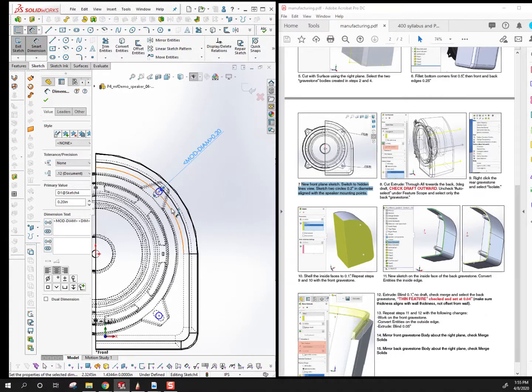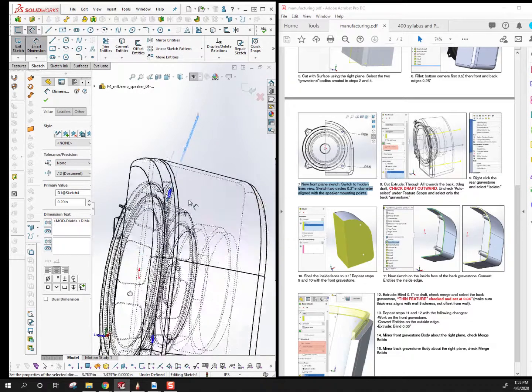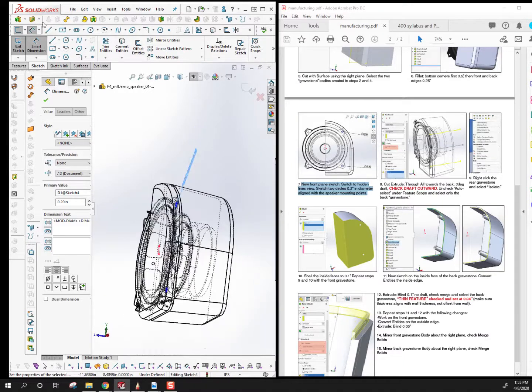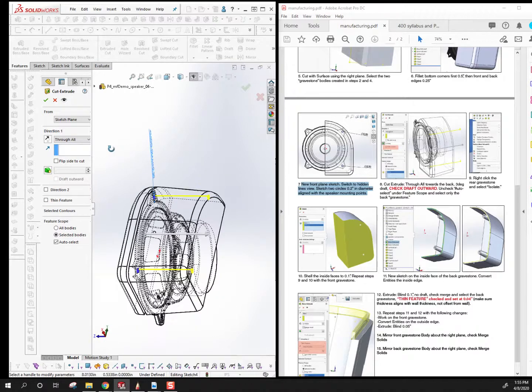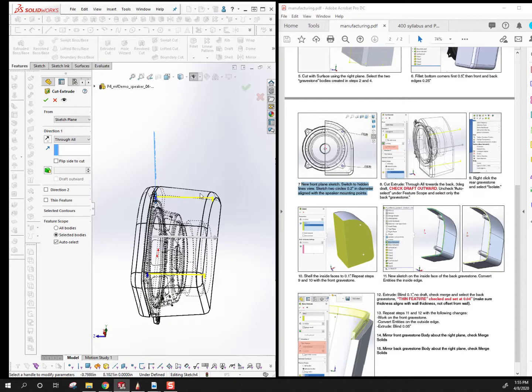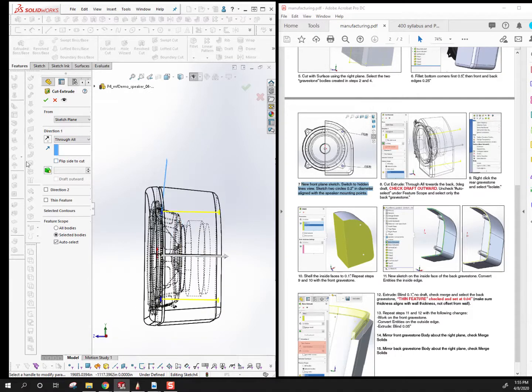And now what we're going to do is create a cut with a draft. So here's our sketch. The sketch is done. While we're still within Sketch World, we immediately go to the feature command here and click on extruded cut. And we can now match some of these settings. So for example, instead of doing blind, I recommend doing through all. This makes your Jenga tower more robust. Like if your object grows longer on your redesign or based on feedback, the cut will always go all the way through it. Now here you want to click again on draft.